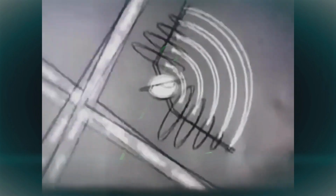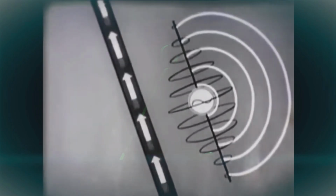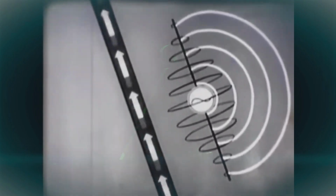How can we use this device as an antenna? Very simple. We spread the wires apart. Presto, a dipole antenna. Notice that the current flow is in the same direction in both conductors, or in other words, the same in both halves of the antenna. The direction of the magnetic fields is now the same, and instead of opposing each other, they strengthen each other.